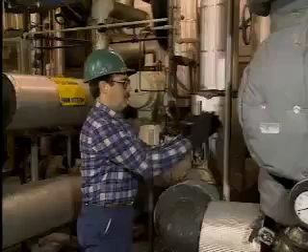During shutdown, the side of the heat exchanger with the hotter fluid is usually shut down first. This helps to prevent the heat exchanger from being overheated and damaged. Let's watch an operator as he takes a heat exchanger out of service. In this example, the heat exchanger, which cools a product from a reactor, is being shut down for maintenance. The tube side fluid is the hotter fluid.